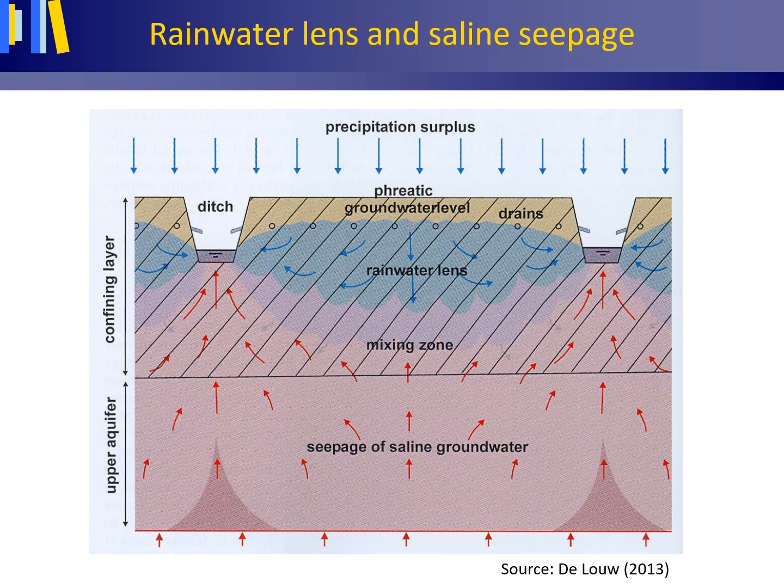picture. A picture taken from the PhD thesis of one of our former Utrecht University students, Dr. Perry de Lauw, where a shallow rainwater lens overlies saline groundwater with a brackish mixing zone in between, and where also the saline groundwater is shown to be reaching the surface water by upward seepage along a preferential pathway.